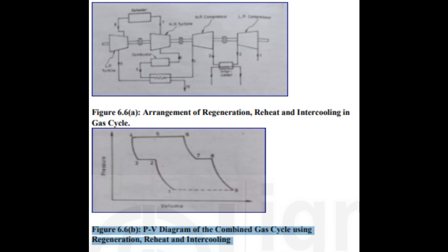6.5 Summary. In steam power plant, one, the purpose of regenerator is to heat feed water by utilizing the heat of steam partially expanded in the prime mover, thus reducing the irreversibility and increasing the plant efficiency. Two, the purpose of reheating is to achieve desired wetness of the steam by heating it after part of its expansion from the turbine, thus increasing the cycle efficiency.